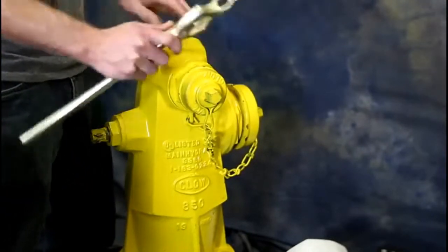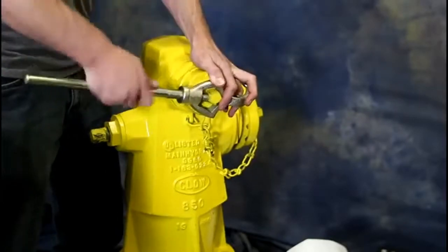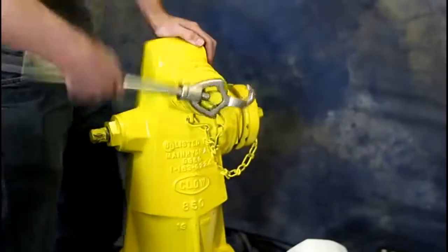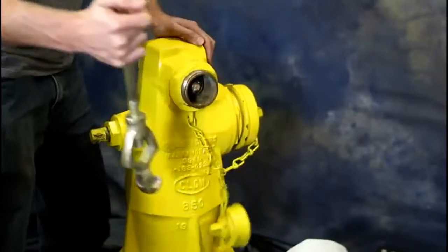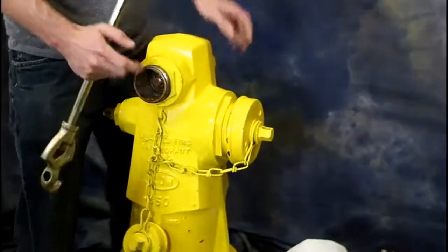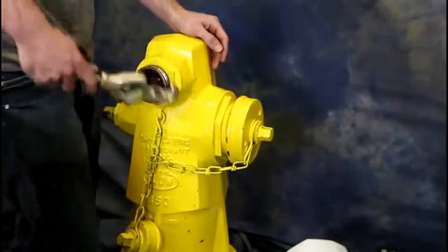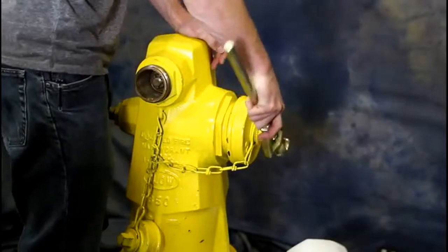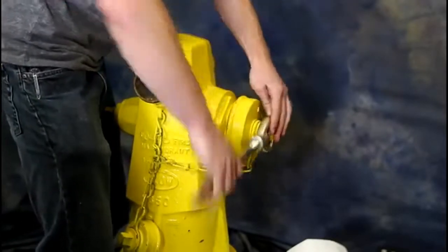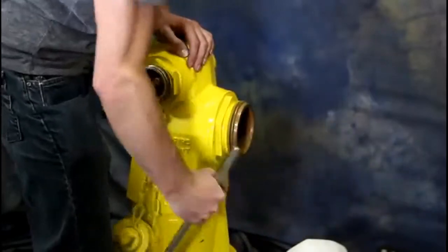So we take this hydrant wrench, which is a hydrant and spanner wrench, and stick it right on, tighten it up, and you can break these loose. Sometimes it takes quite a bit of force. This one's really easy because we've opened it a lot, showing you guys on these videos, but a lot of times these things will be covered in paint, they'll have some corrosion, so sometimes you've got to really work at them, which is why it's good to have the wrench that gives you a lot more leverage.